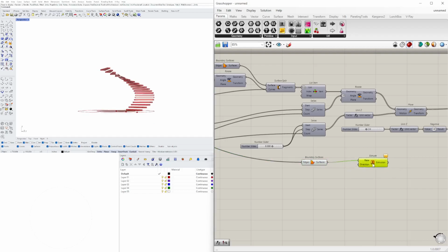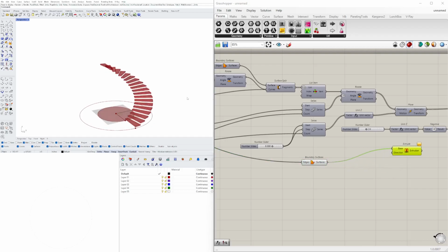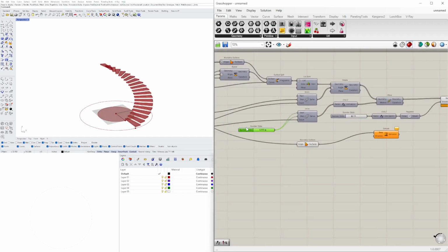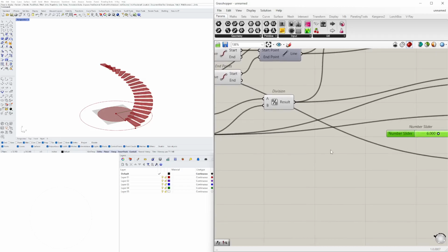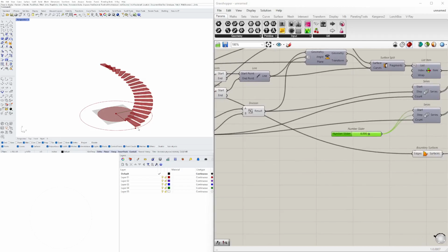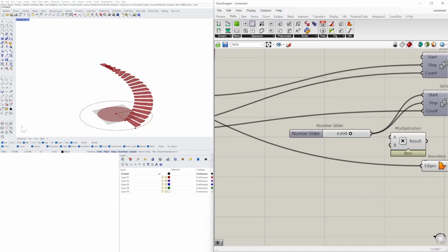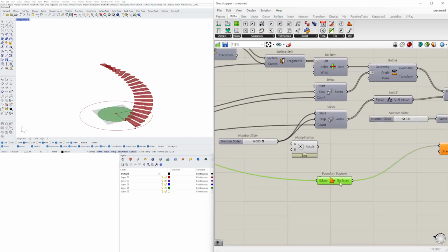The way to calculate how far did we go up, because we did it in steps: 6 multiplied by 20. 6 inches for 20 treads. So I go here to a multiplication. So I'll go to a star, enter. You can always go up here to math, multiplication, and bring it in.